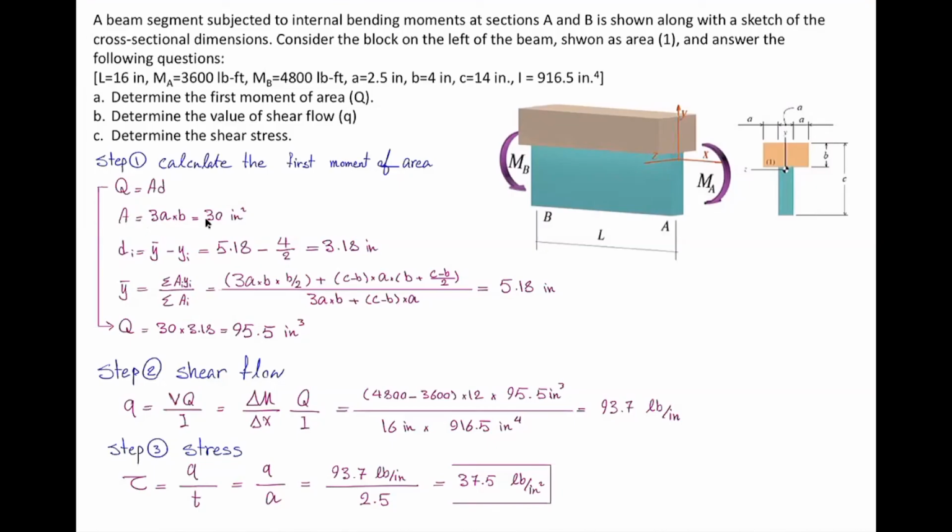Q is now 3 times higher than the first case because we are determining the bending stress that is developed on the entire tan block. That is now 3 times larger than the previous case. Okay. On the last one, you had 2 blocks. Why didn't the other block count into the calculation?